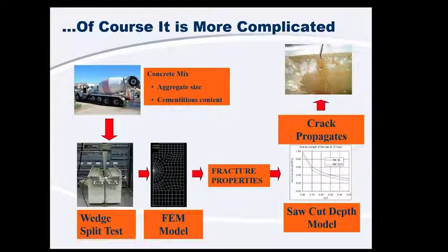So now all of this is a lot more complicated than our typical recommendations. It's from a lot of field experience, a lot of testing in the lab, a lot of computer simulations, finite element analysis, fracture properties of the material. All of this has gone into modeling of the saw cuts and how the crack's actually propagating, but it's basically encompassed in those recommendations on the previous slide. You can see here, actually, this is a great picture of how an early entry saw cuts a very thin cut into our pavement, and it activates right where we want it to.